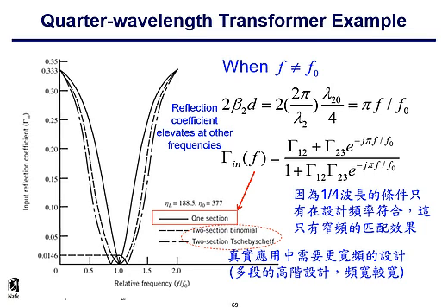For engineering problems, it's a trade-off. To achieve better broadband matching, the result is that your matching circuit becomes very complicated. This is the higher order design, a more complicated structure. So usually the solution to the broadband problem is a higher order design.